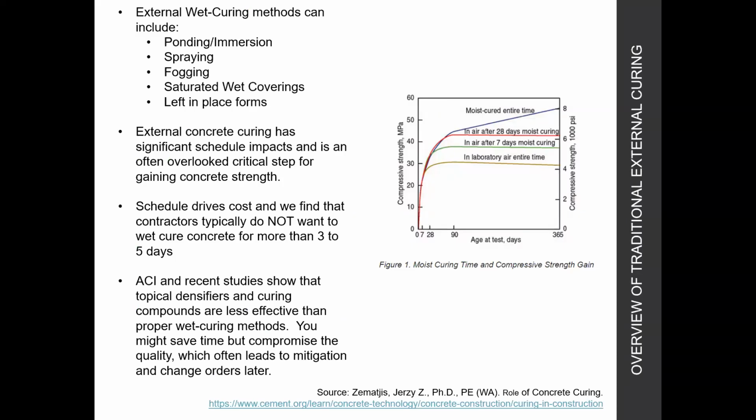The need for the cement to gain its strength, to have time to cure, is really the most important part in attaining a high strength, durable, high performance concrete that's going to have a long life. As you'll see in the diagram to the right, the yellow or gold line at the bottom doesn't have any cure time. If you cure it for 7 days, you gain significant strength, about 20% or so. Another 3 weeks, to 28 days, you gain another 15-20% of strength. And if you cured it indefinitely, that strength would keep rising, actually.